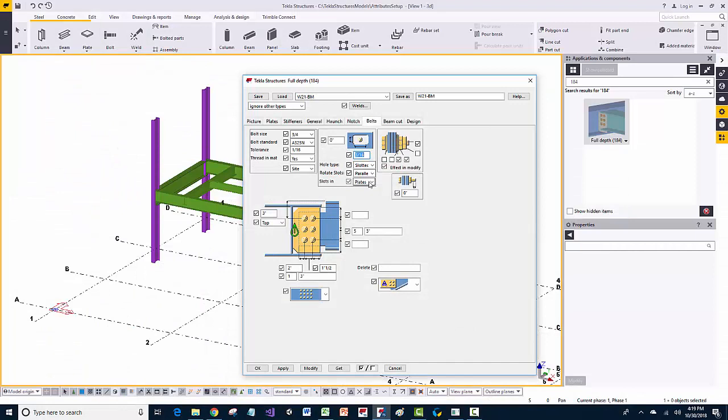And then if you say slots yes or no, what it's going to basically do is switch this between no versus slots in angles or slots in plates. In your standard or your seed file, you're going to want to have this as slotted if you do want slots versus oversize. And I believe default will also read slots because it's set that way in the joints.def file. But in your standard file, it's probably a good idea to set this. And what the tool programmatically does is it changes this value here of being in plates and angles or no if you don't want any slots there. And then you just decide what the slot length is in this value here.